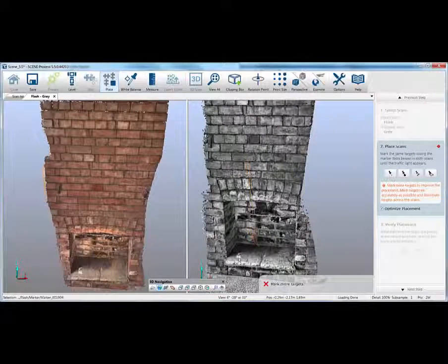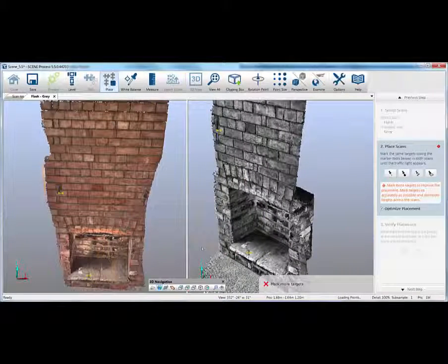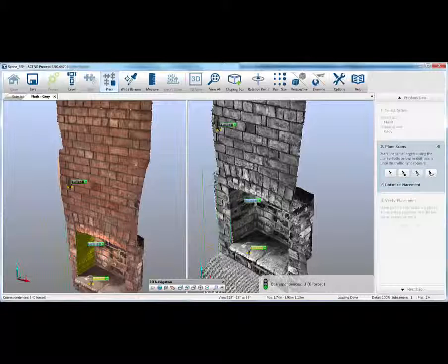And I think we've got this colorization on the floor here and this pattern, so I'm going to put a point at the end there and a point at the end there. We've got these metal brackets up here, so I'm going to put a point roughly at the corner of that metal bracket, and then, just to give myself some deviation, I'm actually going to mark a plane on that brickwork and a plane on that brickwork. So straight away we've got our 3 points. If we hadn't matched those 3 points in such a well-mannered fashion, then the system would keep telling us to mark more points. So it's trying to give you more feedback on what it actually needs in order to do the registration.